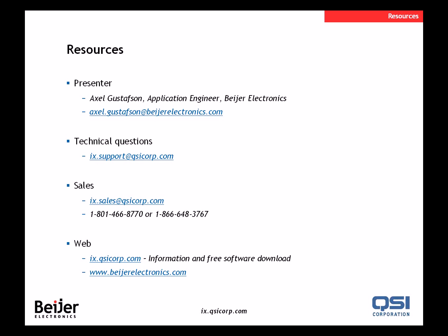What you then would do is change that to a PC application, and you can select what resolution you would like to use. It will do its best to resize the objects to fit the higher resolution of the PC. Some objects you will need to tweak a little bit to get them to look right. You might need to change some font sizes, but the majority of the work will be done by IX Developer for you. Gary asks, what are options for managing many more screens, say 20?